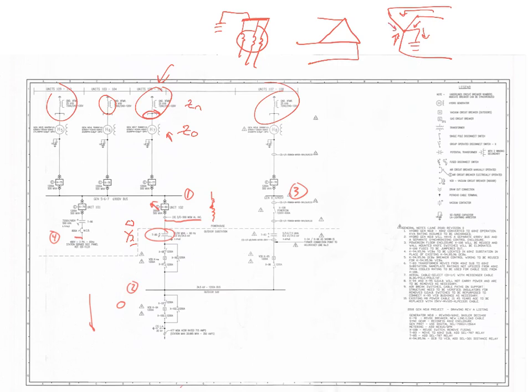Can a current in here flow through here? Well, as long as that current can flow through here and flow through here, right? So these are all 0 sequence currents who all have the same value. So that current circulates in the delta. This has to equal 0, doesn't it? All those currents have to be equal to 0. But I can have 0 sequence current flowing in the delta side. I just can't have current enter or exit the delta side of the transformer.